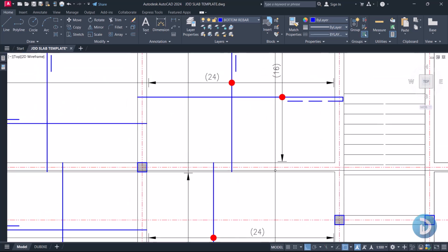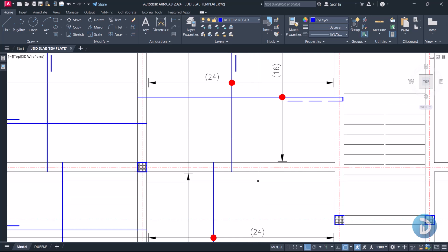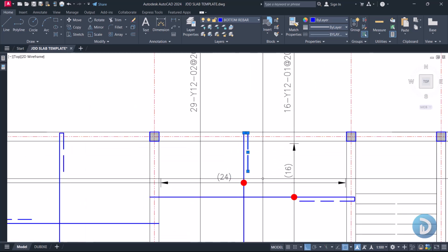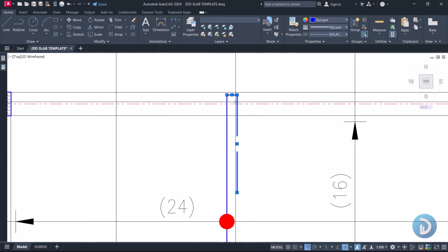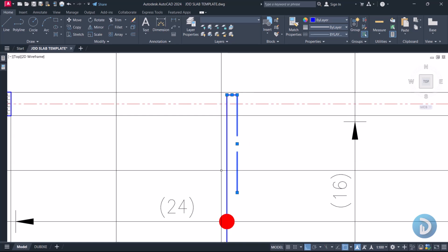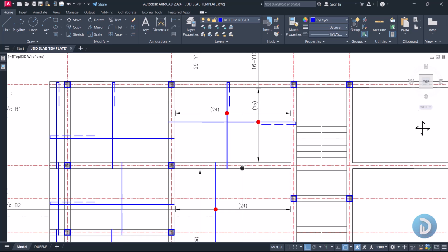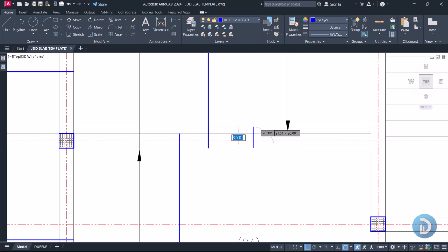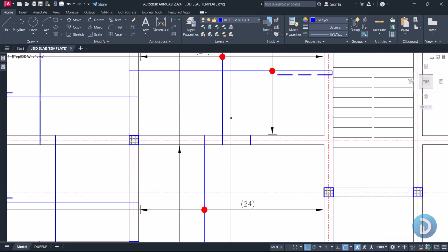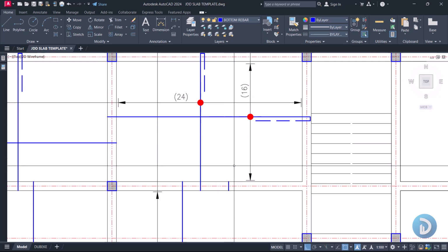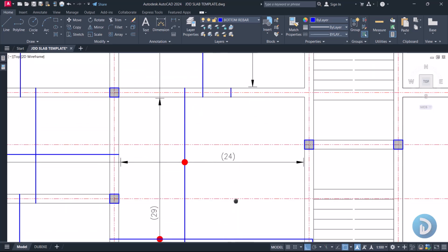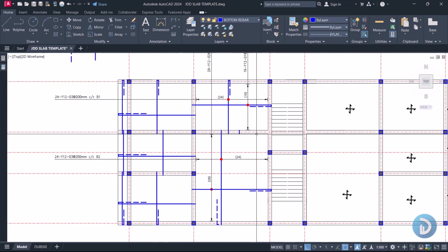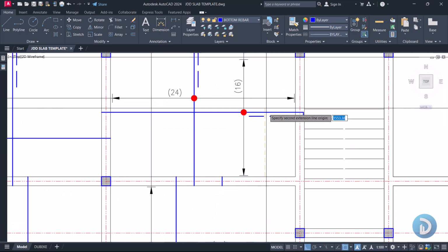So our top reinforcement, we will start with this acting on the beam areas. Do not forget that we already have one set of the top reinforcement here, which is connected to the bottom reinforcement at this part. Okay, so let's start with this, and for this we should be having this from this to this panel. Then we also have to go here by 25% and also go to this other panel by another 25%. Okay, so we'll come here and we'll dimension this.